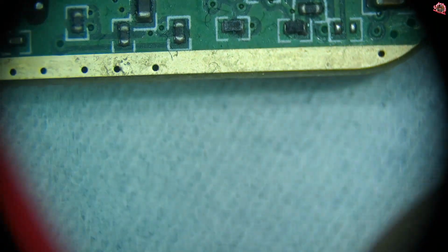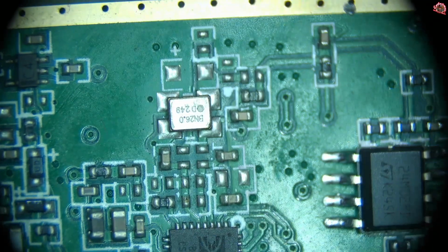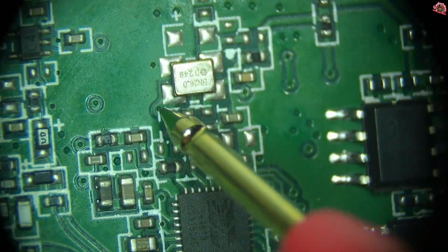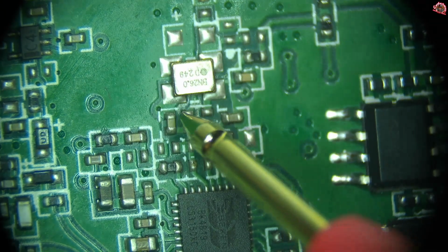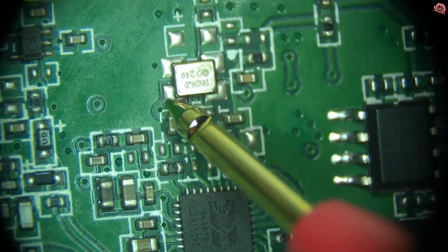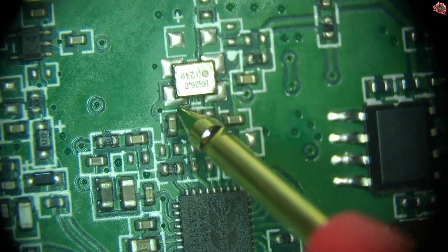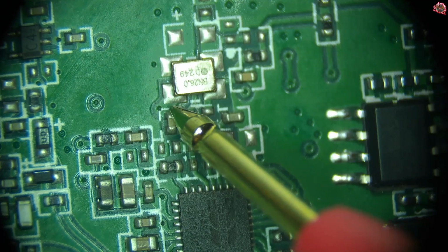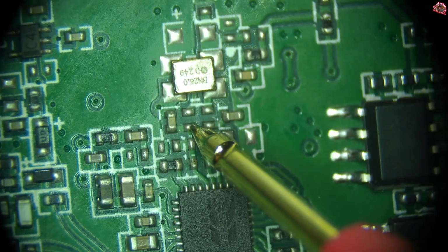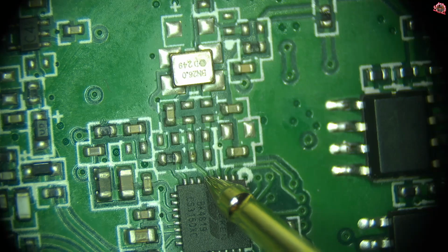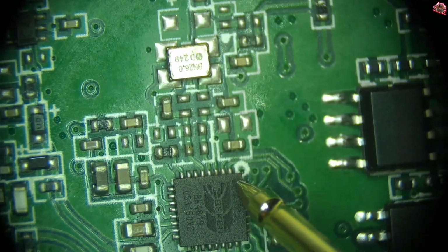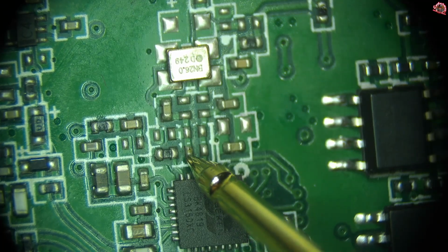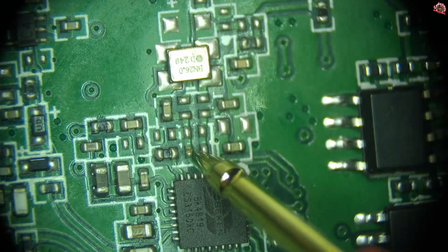And I've already done some research of camera. This signal comes out of here. You see this via right over here and to here. So this is the output from the oscillator. It's 26 megahertz output. This is ground, and through this capacitor the signal goes right in here onto this pin, which is 1, 2, 3, 4, 5. This X I oscillator input pin.